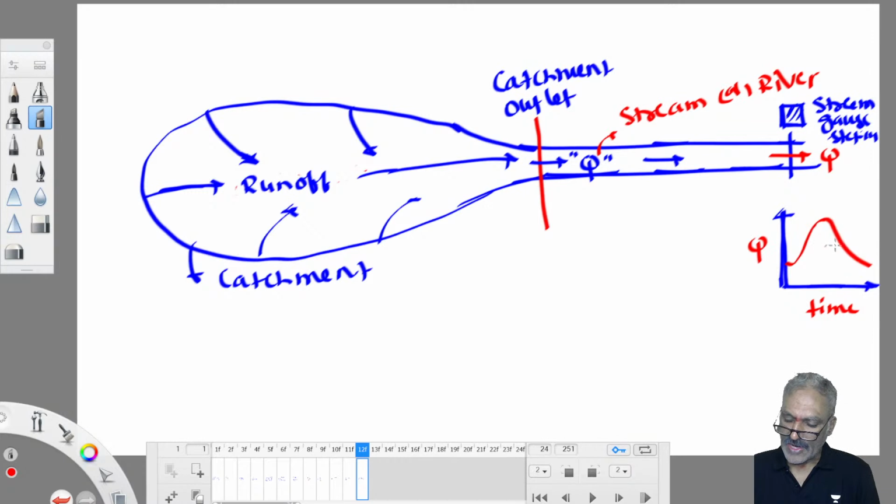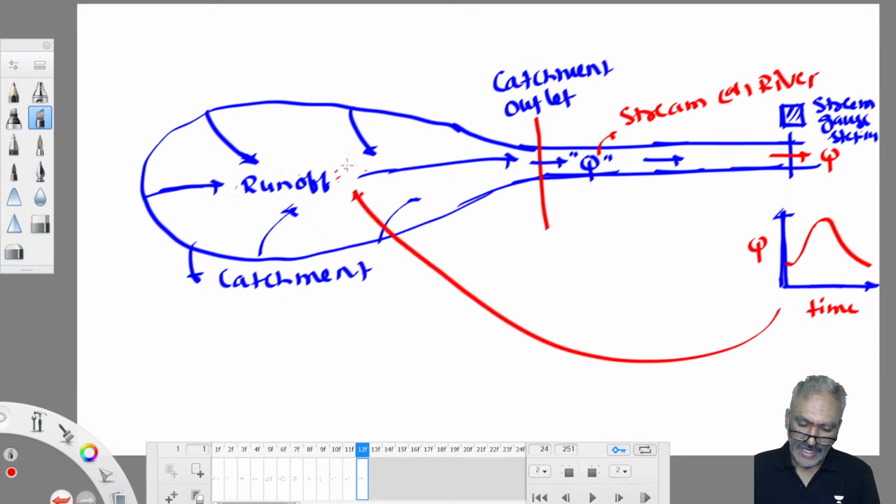That's how we measure. By using this, we try to arrive at the runoff component. Using this hydrograph, we try to find out how much runoff the catchment delivered. So this hydrograph is a plot of the time distribution of runoff. It is an output produced by the catchment for a given input rainfall.